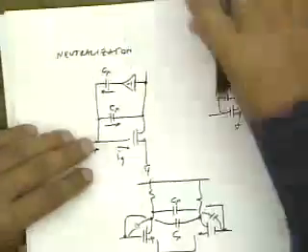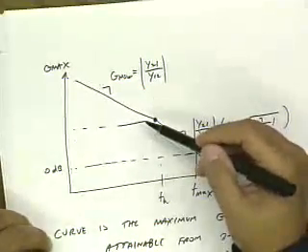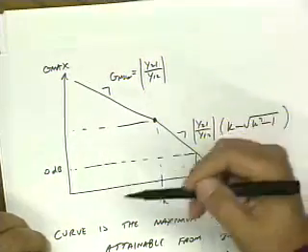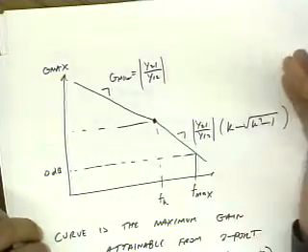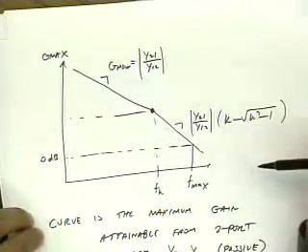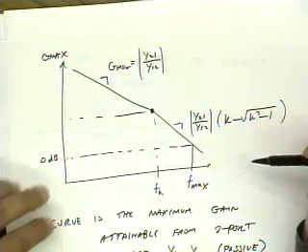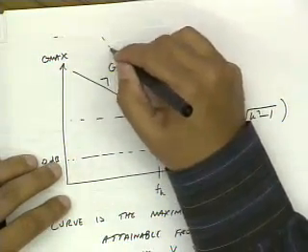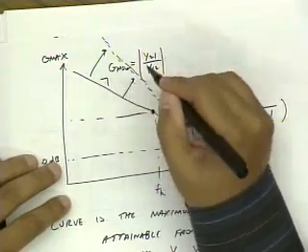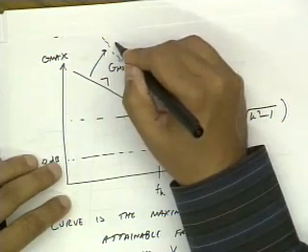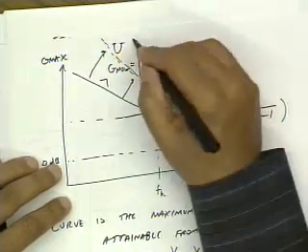Okay, coming back to this curve, what you find is that in the case that your device is unstable, if you unilateralize it, then it becomes stable by definition, right? Because you're getting rid of the feedback. And then you can use this formula again for maximum gain of a unilateral amplifier, and you'll find that you can actually get more gain. So this is what we call the U, or the unilateral gain.